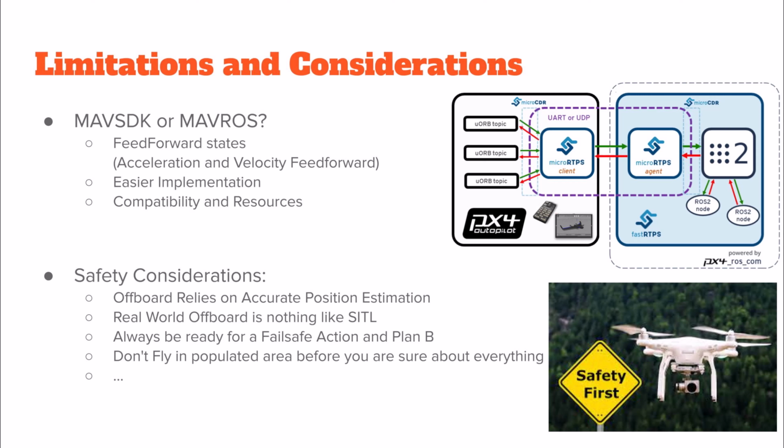But for some very advanced trajectories that need very precise trajectory following and sudden change of direction, you might need acceleration feed forward as well. You can still use MAVSDK and create the acceleration setpoints manually by creating some new MAVLink commands while using MAVSDK. But many users try to use MAVROS in these projects.